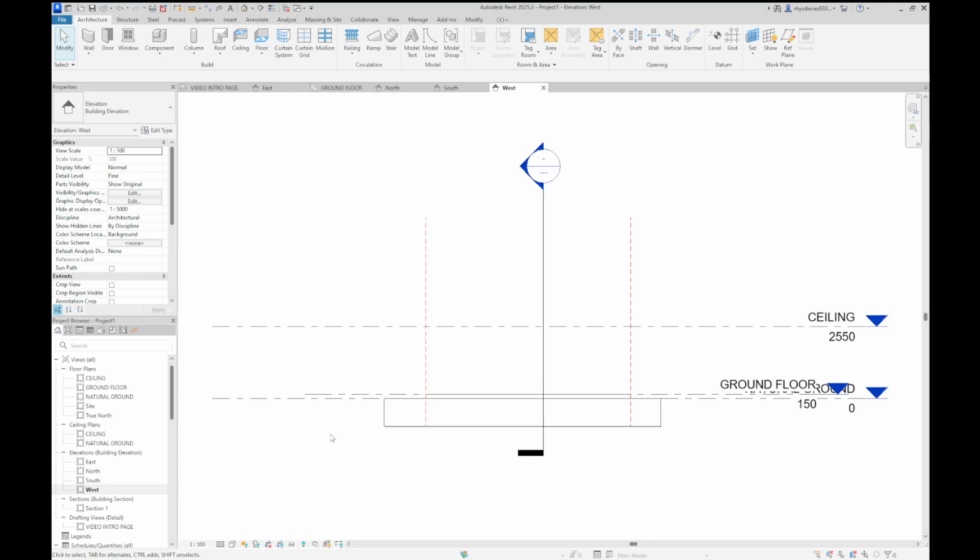The floor and the topo solid commands work basically the same. And in fact, technically you could use the floor for a topo solid and vice versa, but it's not recommended when you are doing fancy stuff like scheduling, because it will count a topo solid. We don't want a topo solid to be read as a floor and vice versa.